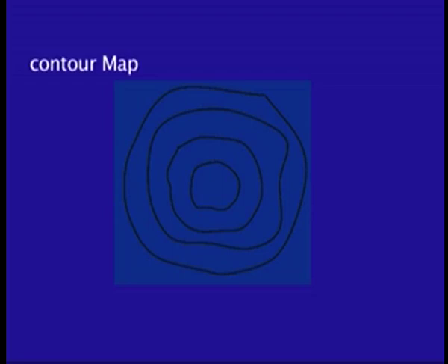all the various points or the various locations, these could be some landmarks, it could be the top of a building, or it could be the bottom of a building, or it could be the top of a tree or the bottom of a tree, and so on and so forth, the various landmarks, or it could be just the surface of the earth or soil. Points with the same altitude or height are joined by a curve, and these are called contours. And then you have a set of such curves for various values of the height, and such a map is known as a contour map.